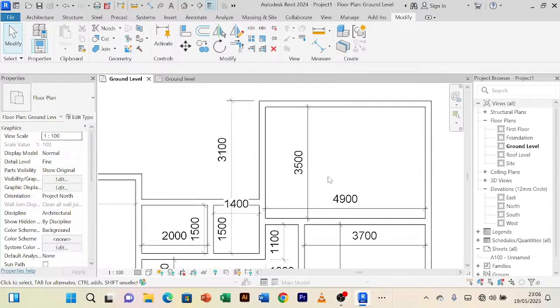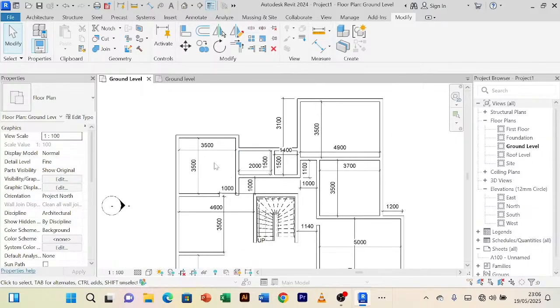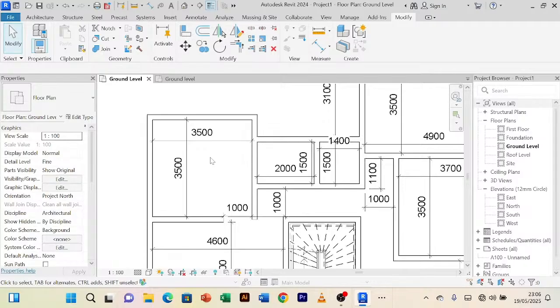The reason why you measure the interior sides of the house is because in detailing, when you give details about your measurements, if I tell someone the room is 3.5 by 3.5, and for you here you have measured using either the exterior or the center line of the walls, the measurements will take the wall thickness as well.